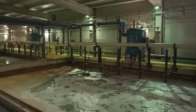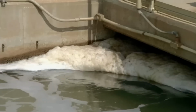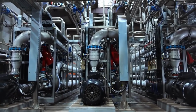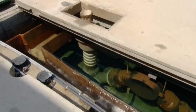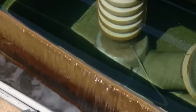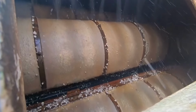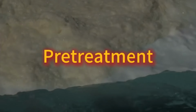Ocean water contains suspended sand, silt, microscopic organisms, organic material, and minerals. All of these can interfere with the equipment further downstream, particularly the reverse osmosis membranes. A layer of biological growth or mineral scale on a membrane makes it harder for water to pass through, increasing the pressure and energy required to keep the plant operating. So the first major stage is pretreatment.